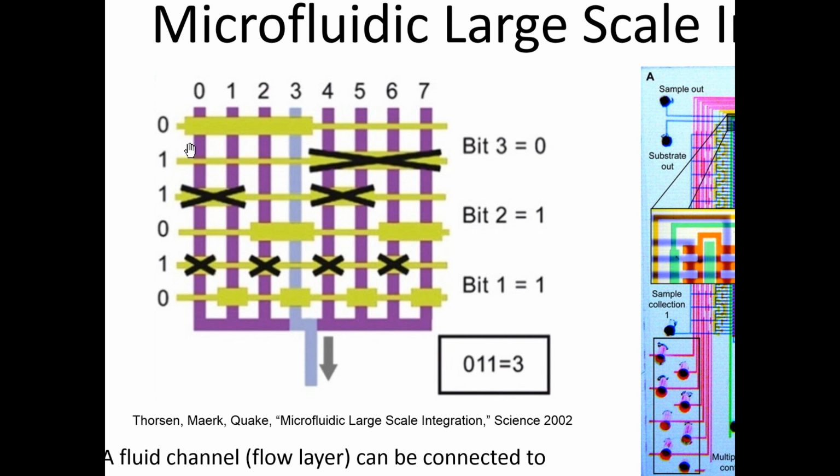So they make the pneumatic channel wider in certain patterns, in certain regions here. In the regions that are wider, these valves have a larger area, so they're able to deform at a certain amount of pressure.